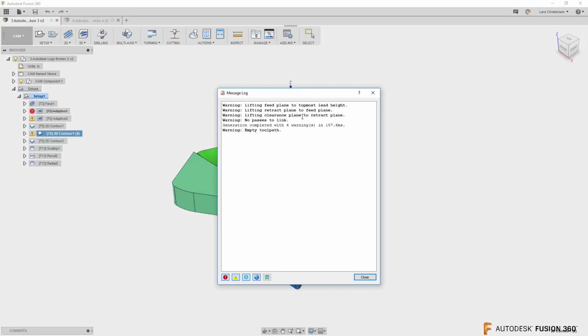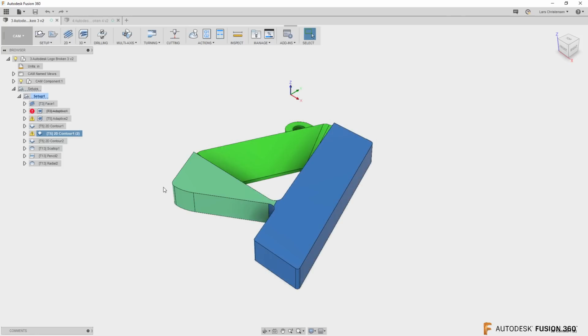This is actually where the cutter cannot fit in the selected area in here. And another thing I wanted to show you, if you ever get these warnings, if I click this little bit in here, it will show down in here none, versus a toolpath that actually works, it will show you a kilobyte in here. So this is another indication that the toolpath is not there.